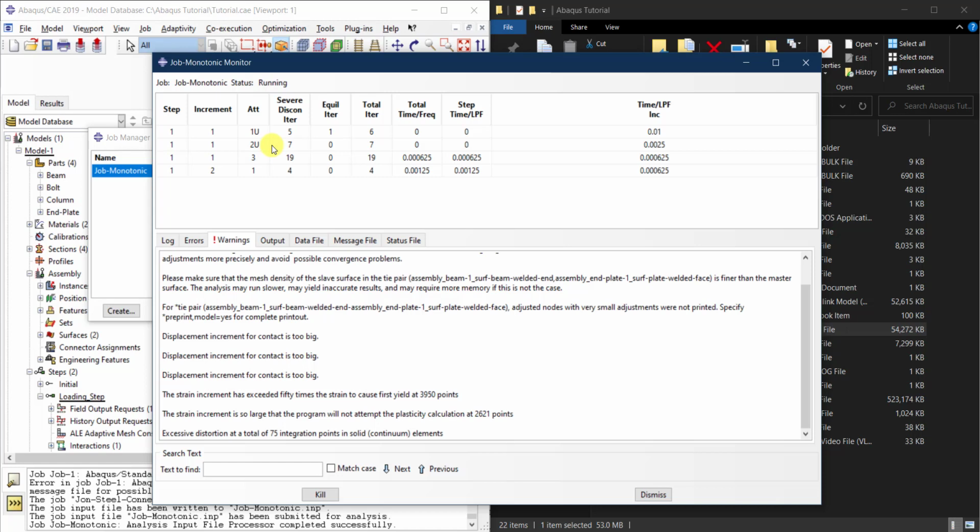So you can modify these things later on. You can apply it in a ramp, maybe in a different step, so that this doesn't happen when you apply a very large load instantaneously, all of a sudden. But right now, you see, we are going better. ABAQUS has resolved this issue. You had some problems with severe discontinuities and so on, but right now you are moving ahead.